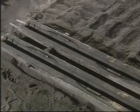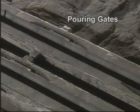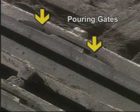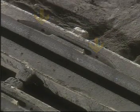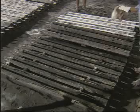During the preparation of the drag, openings called pouring gates are provided to permit molten iron to enter the mold cavity. NECO has developed the side gating process to give better flow of the molten iron, which in turn results in castings of more uniformity in thickness and less chances of pinholes and blowholes.